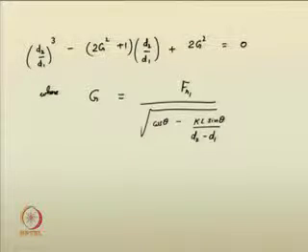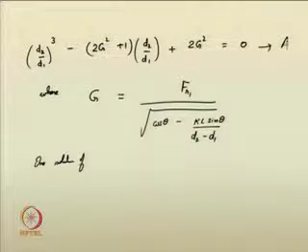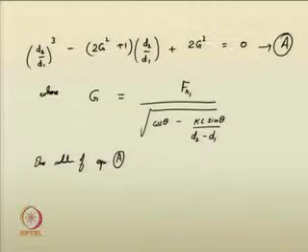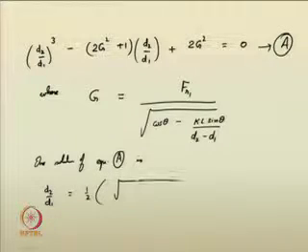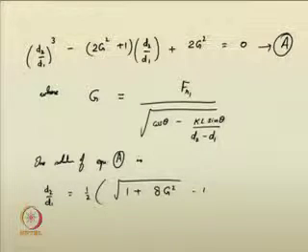So, if you define G in this way and incorporate it, you can see a third degree polynomial or an equation with respect to D2 by D1, and that can now be easily used. You will see that one solution of this equation, say if I name it as A, one solution of equation A is D2 by D1 is equal to half of (root of (1 plus 8 times G squared) minus 1).